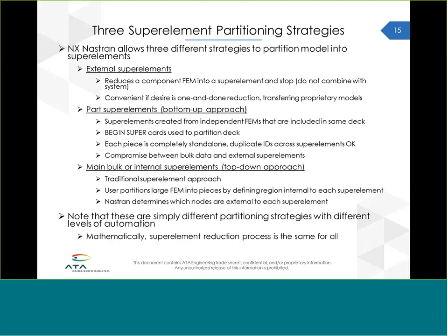Main bulk, I think this is the most common superelement approach. It's when you have a single FEM which is complete and is valid without superelements. But what you, the user, are doing is partitioning that and telling it what portions of that model are inside of each individual superelement.